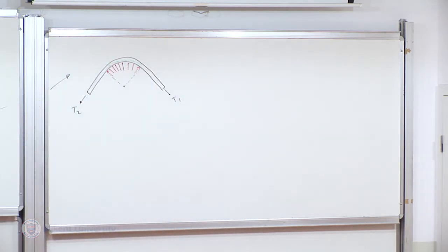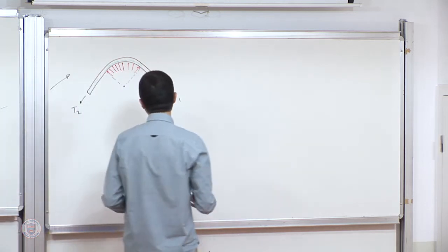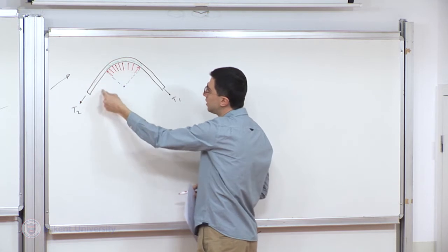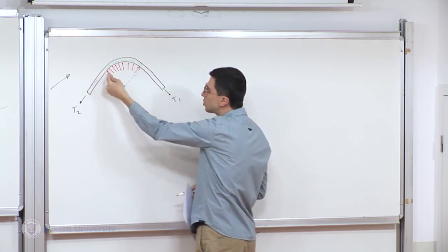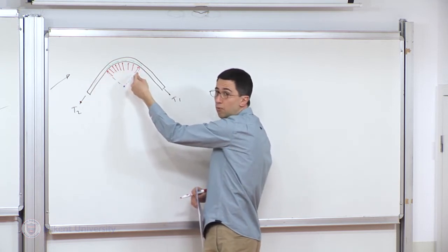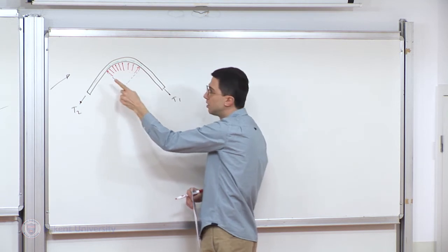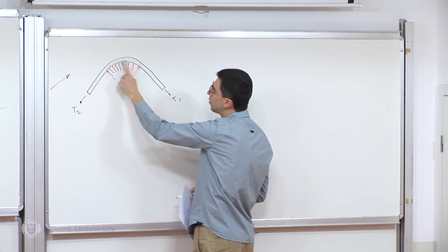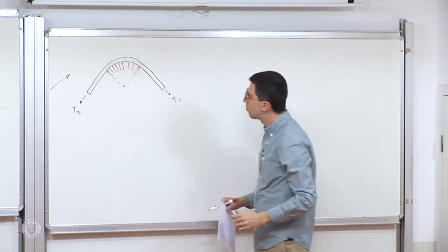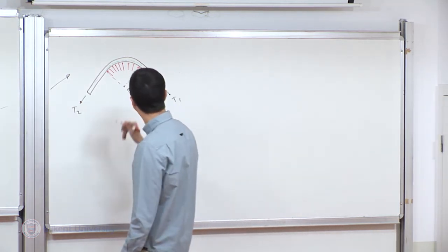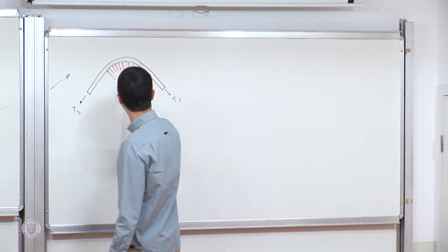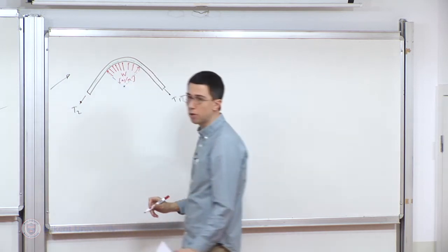Now the rope we can idealize, or think of it as contacting the cylinder here on a line. So this force is going to be force per unit length. So if I integrate the red normal force along the length, I will obtain force in units of Newton. So let's call this W. Okay, W is Newton per meter, force per unit length.